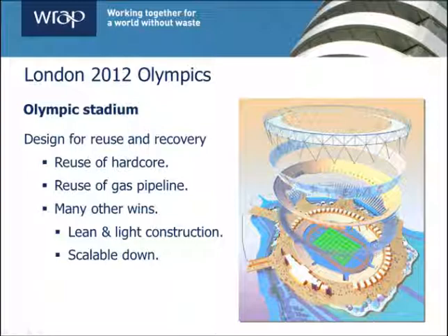In this slide, we are just focusing on the first of the 5 principles of designing out waste, design for reuse and recovery. For example, 140,000 tonnes of recycled, crushed concrete, originally brought onto the site for use as piling mat, was reused in the permanent works, reducing the quantity of virgin aggregates required, saving £1 million and eliminating more than 20,000 lorry movements.